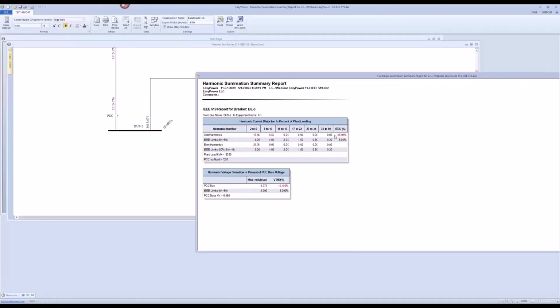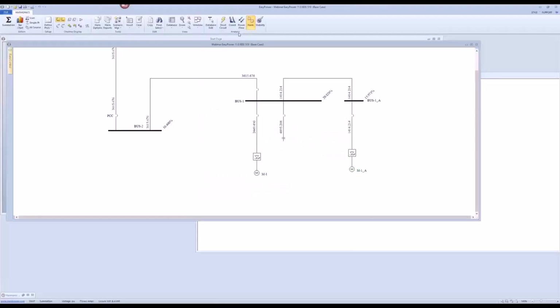Of course, I follow the same equation to calculate my ITDD, and follow the same way of calculating the ITHD as well, to include every one of them, right? So in that case, I have my maximum voltage as well. We will take a look at where it is, and what the VTHD is as well. You can see that right now VTHD here 10.4 is equal to 10.4 here, right? Because we did not include any of the harmonic orders larger than 50.